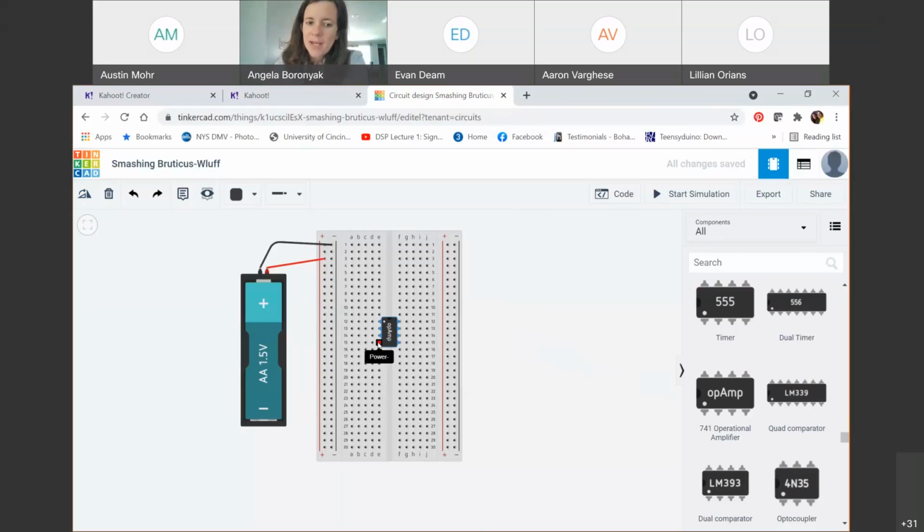Keep up with that. Here's my non-inverting input. Here's my power supply negative. They're a little clearer. Here's my power supply positive. Here's my output. We're not going to do anything with these pins, offset 2, offset 1, and the not connected pin. Some of the time you might do something with them, but it's rare. Those are the more common.